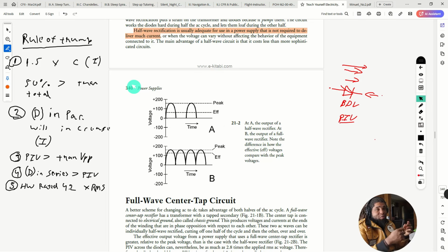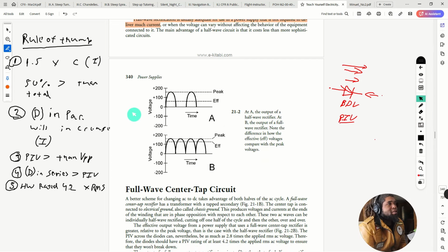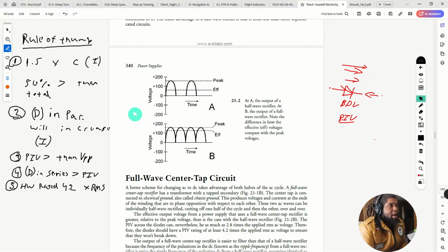And that makes it also very simple for us too, right? On top of that, it doesn't need very consistent voltage. It can fluctuate. It could probably be plus or minus 2 or something like that for a fixed bias on a guitar amplifier. So that's the situation in which having a half-wave rectifier would be fine.